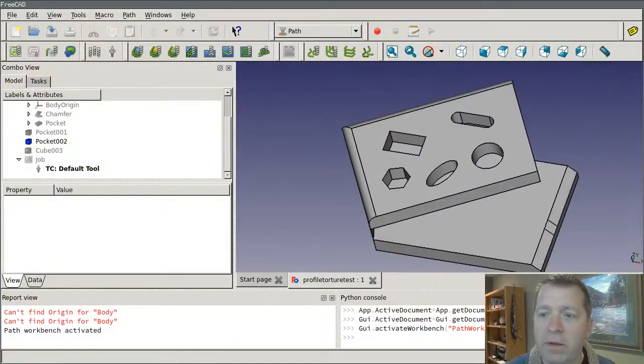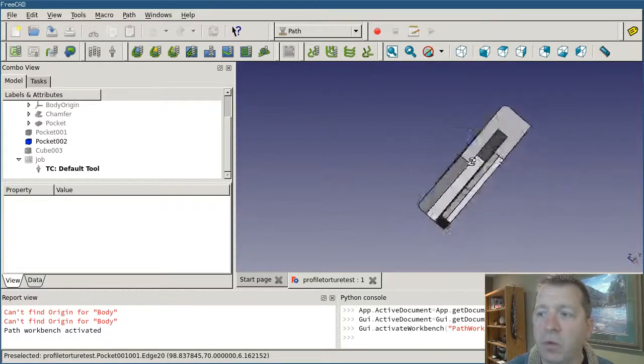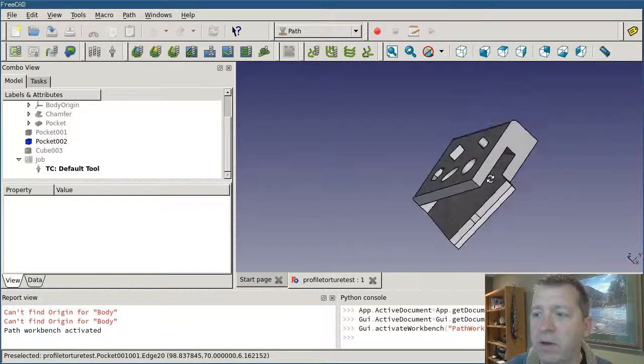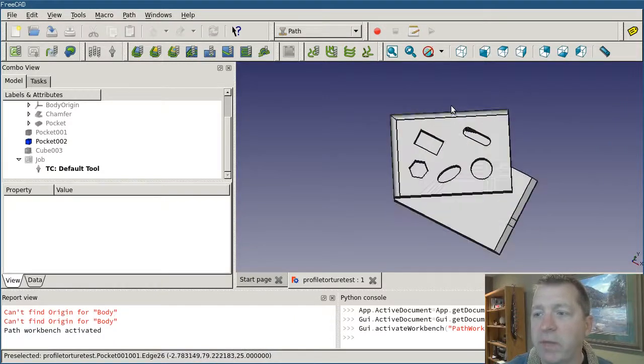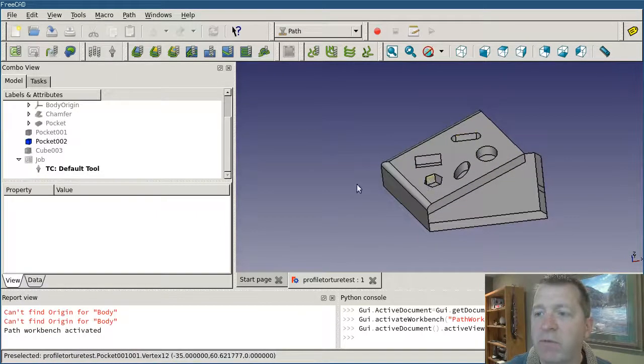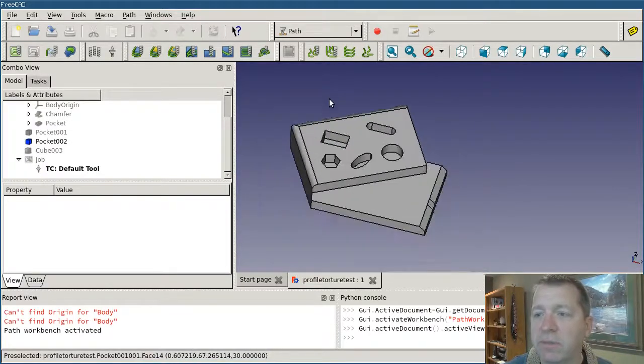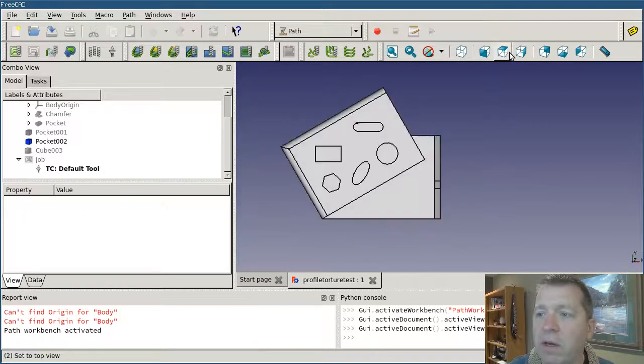So what I've got here is my contouring torture object. It's got a deep undercut on it. It has an irregular shape and some surface holes. If I were to try to make this part out of wood or metal, I would do the internal features and the top surfaces first, and probably the last thing I'd want to do is to cut the whole object out of the surrounding material by doing a profile operation and stepping down to depth.